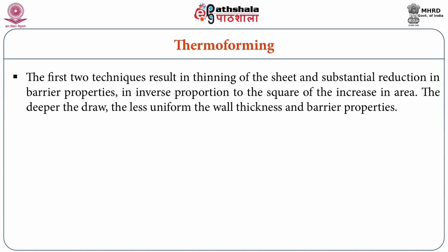The first two techniques result in thinning of the sheet and substantial reduction in barrier properties, in inverse proportion to the square of the increase in area. The deeper the draw, the less uniform the wall thickness and barrier properties.